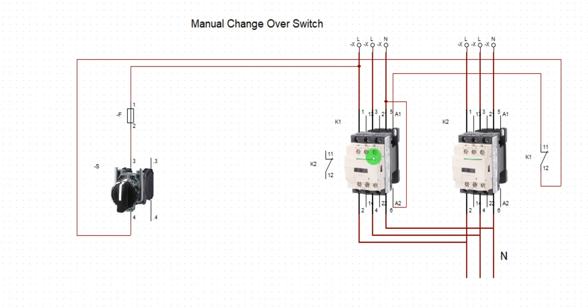Alright, see the wiring, the connection process. Before I send power to this contactor, I take from the supply source, the supply input side of the contactor, and take it to my fuse. From the fuse, I go to the switch. From the switch, I travel all the way to this contactor and go to the auxiliary of this contactor. This is the auxiliary.